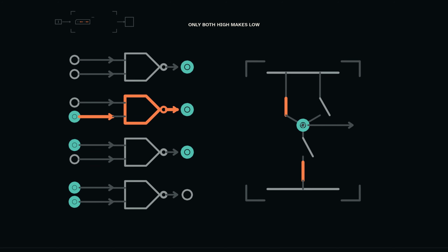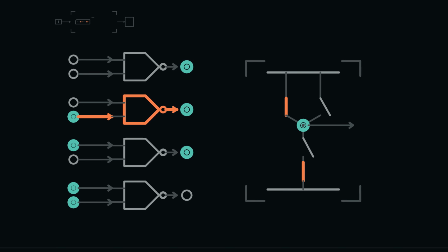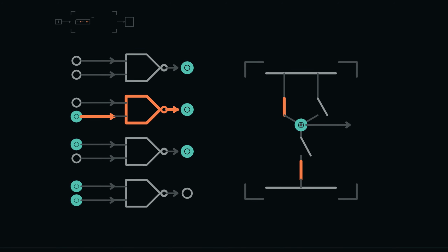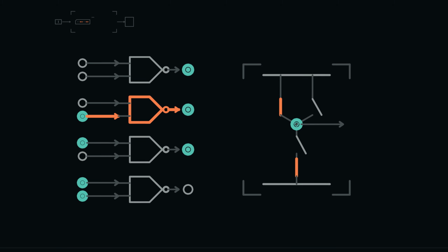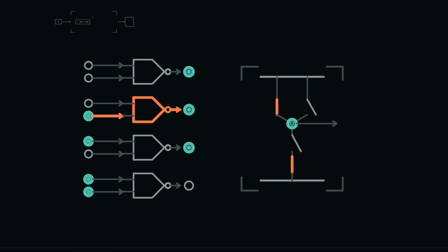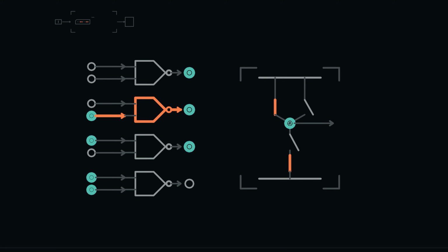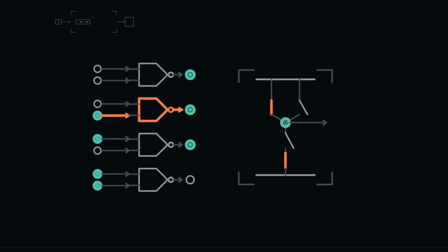Its output follows physical behavior within electrical and timing conditions. The table assumes every input is an accepted 0 or 1. An invalid voltage is outside its promise. Physical output also changes over finite propagation time. Different technologies can use different structures and thresholds while implementing the same table. The table tells us the required relation, not every fact about how matter produces it.